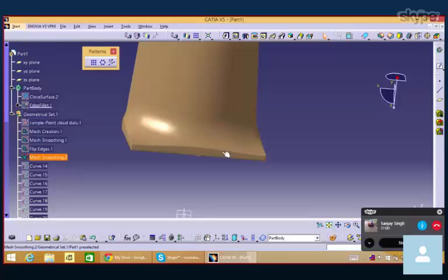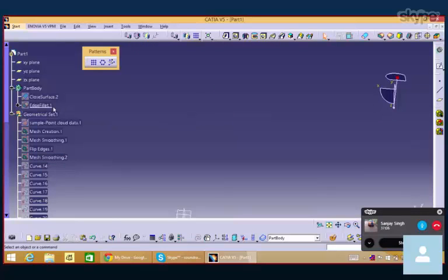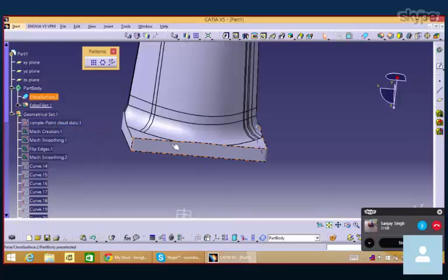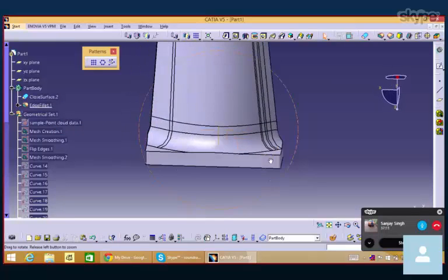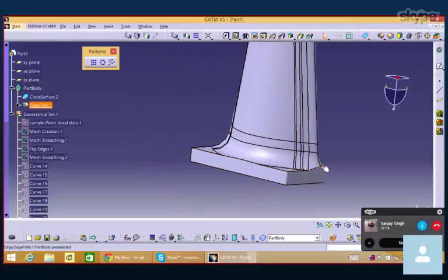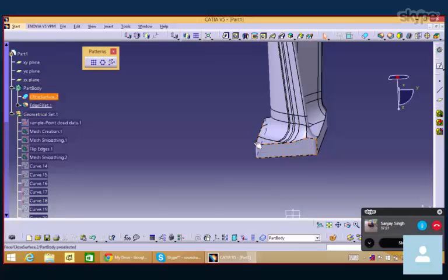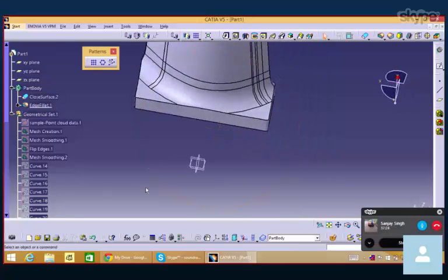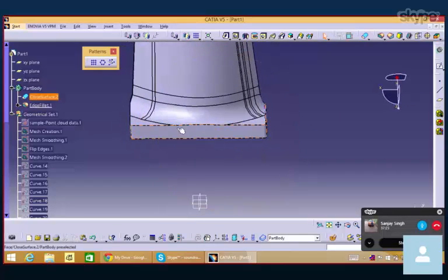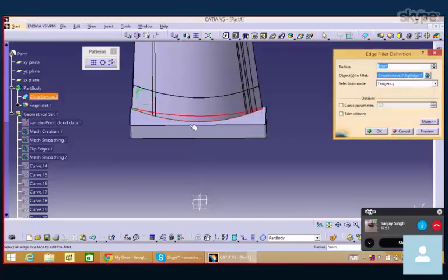Okay, you just hide it again. Yeah, this mesh. Almost we got it, but this side profile, if we give the pillar itself, we got the side profile. Do you see that? Yeah, side profile we got. So this place alone we need some more radius. So here the radius value is maybe higher. Then double click and reduce the radius value. No, give 6 or 7.